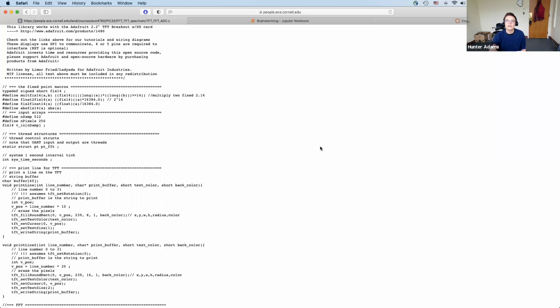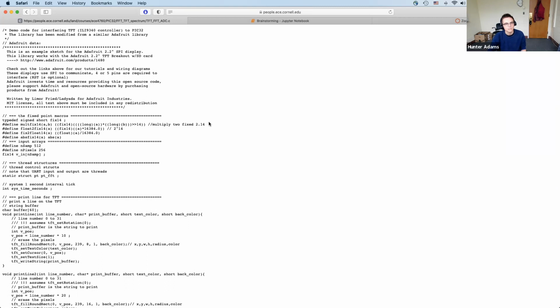the fixed point data type that's being used is one that's created in this file called fix14. You can use that if you want. I would probably recommend using the accum data type that we used in the previous lab, and the version of the function that's written at the top of the Lab 3 webpage is written using that accum data type. So I want to just point you to that. That is the thing to pay attention to in this example.